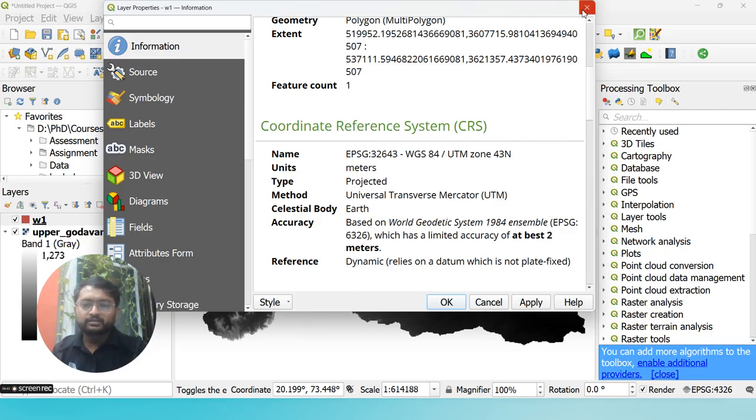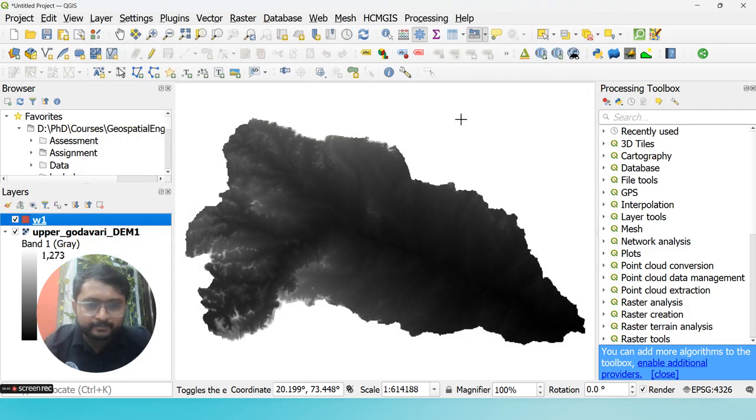Getting my point? Yes, but when I am using a UTM or projected coordinate system, I am getting the planimetric area. But the real ground area is different from the planimetric area. So what you have to do is convert your data into a geographic coordinate system, from UTM to geographic coordinate system. Then it will become in degree, and then I calculate it without the dollar sign, that area, right? Yes. Okay, thank you.